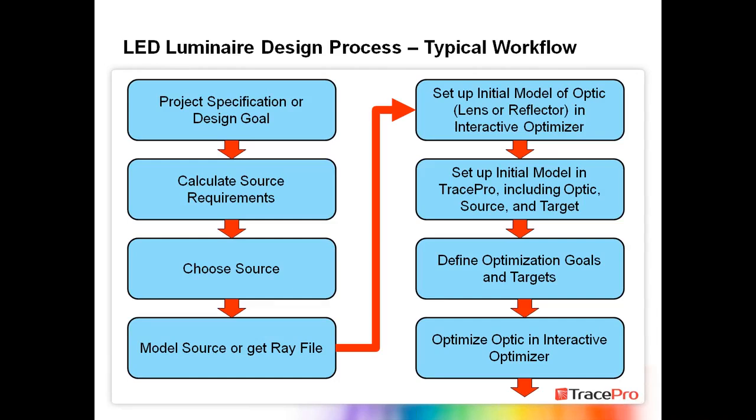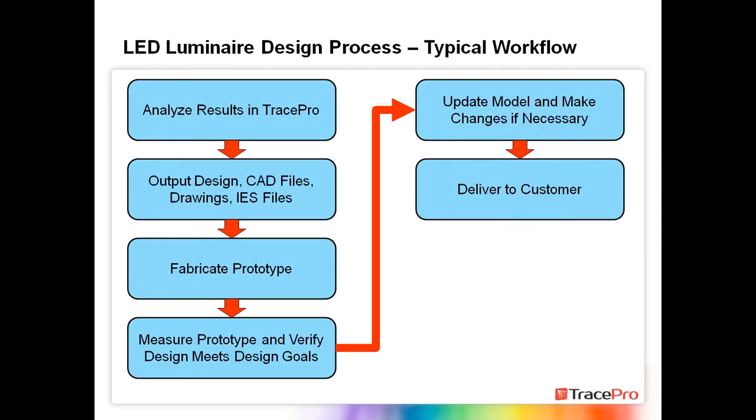Ray files, for people that may not have used them, are a file where the manufacturer has taken their LED. Now, I'll just mention LEDs in this case, but it's really applicable to all sources. But they've had it measured, and they've saved all that data, and they've produced this ray file, where each line of the ray file represents a single ray. And each ray will then have an XYZ starting position, direction vectors, and flux values.